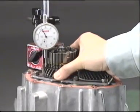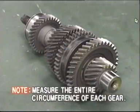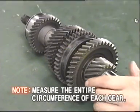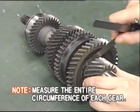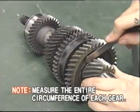Before disassembly, do not forget to measure and record the thrust clearance of each gear. Use a dial indicator for the fifth gear. As for the other gears, use a thickness gauge to measure the thrust clearance. In each measurement, check the thrust clearance around the entire gear circumference.